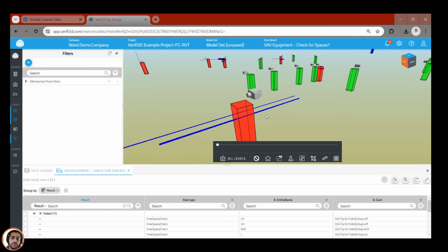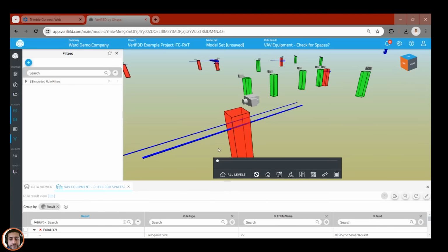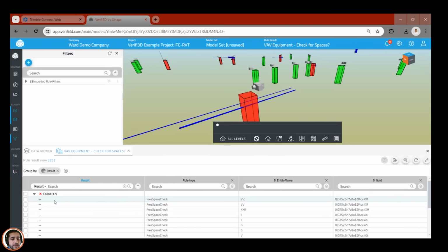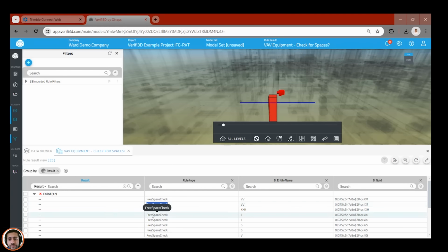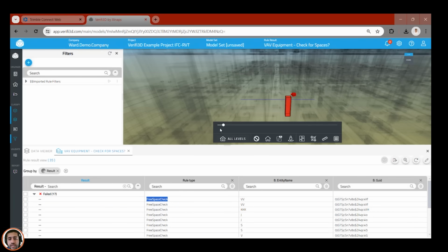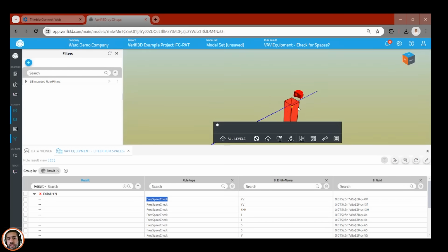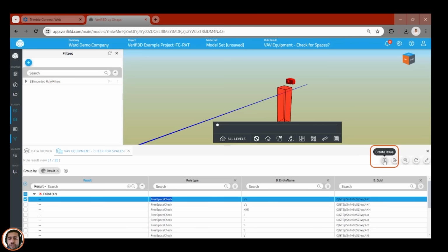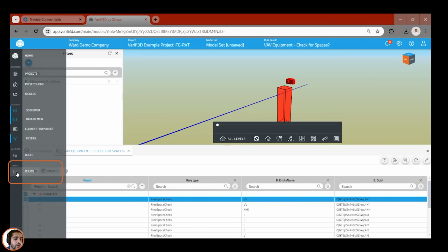So I have a clash over here, some kind of a clash, or let's say an issue. How do we report this to BCF topics on Trimble Connect? The way we do this is, of course, we can select them from here. For instance, I would like to select this one. Then I'll just double click. Of course, you can create an issue. If you specify it from here, you can just create an issue, but I'm going to go to report.